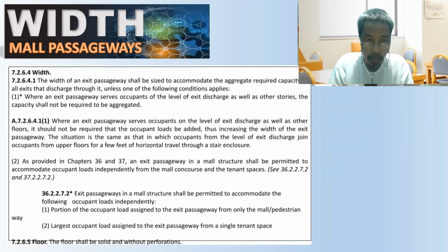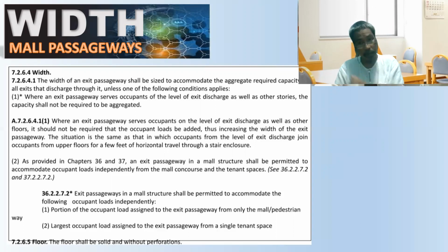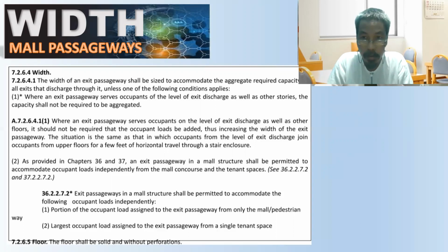But the passageway shall be sized to accommodate the aggregate required capacity. Required capacity means, in terms of occupant load, how many persons are designed to utilize that passageway. So we have to aggregate from all the exits that discharge using that passageway. So that is very logical. And we only have the